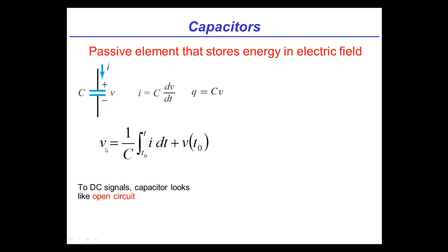That's right, because if you had an instantaneous change in voltage, you essentially have a step discontinuity in the voltage trace, and that's going to require essentially an infinite amount of current. Exactly. And remember, there's no such thing as an infinite amount. An instantaneous change in voltage means dV/dt goes to infinity. If dV/dt goes to infinity, the capacitor would require an infinite current, which doesn't happen. So therefore, what we can say about the capacitor is that the voltage change in a capacitor must be continuous. So a capacitor works to prevent abrupt changes in voltage.